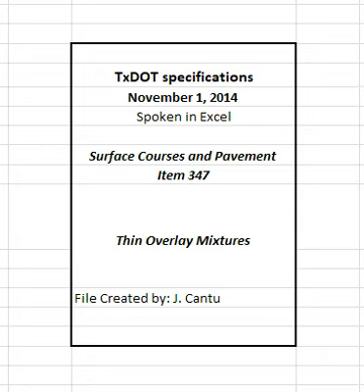4.7.3.1.1.1 Moderate. Any areas that have a temperature differential greater than 25 degrees Fahrenheit, but not exceeding 50 degrees Fahrenheit, are deemed as having moderate thermal segregation. 4.7.3.1.1.2 Severe. Any areas that have a temperature differential greater than 50 degrees Fahrenheit are deemed as having severe thermal segregation.